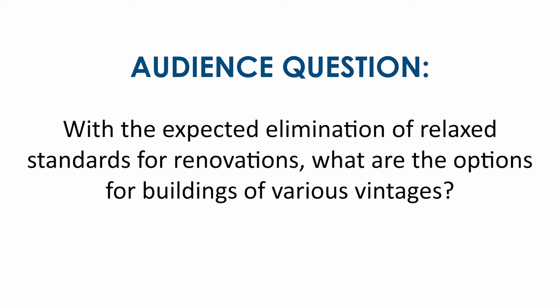The second thing is that usually in that type of situation, adding the insulation wouldn't have a 15-year or now a 12-year payback anyway. And so we would expect renovation projects to pull that lever more often. The original scope of the renovation was lighting and HVAC, but to get to 80%, we also had to do an envelope upgrade, and that had a 30-year payback, so that's why we're not doing it.